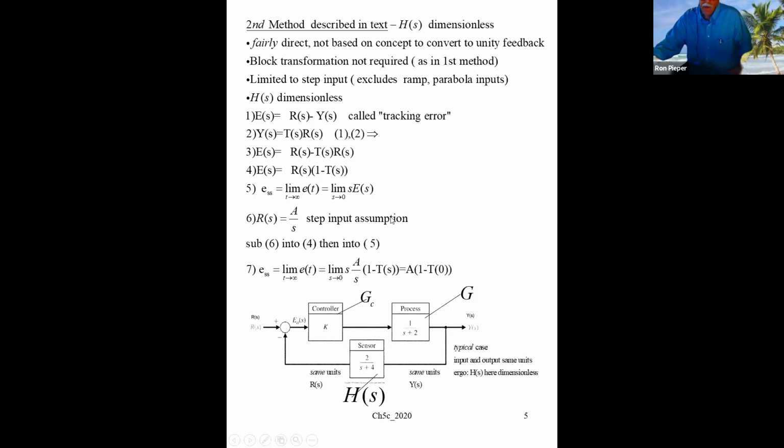And so we'll see why it's so obvious it works. For the step input, you get that 1 over s, but then that s in the denominator for the step nicely cancels the factor of s that seems to be built into the final value theorem rule. So you get that immediate cancellation, and after taking s equal to 0, you get this recipe which completely sidesteps the issue of type analysis, but it does give us the steady state error.